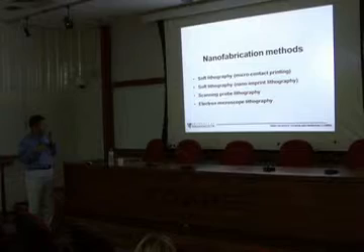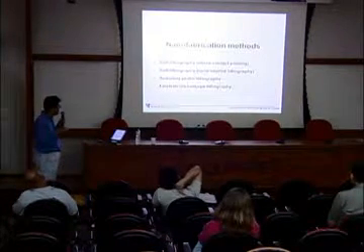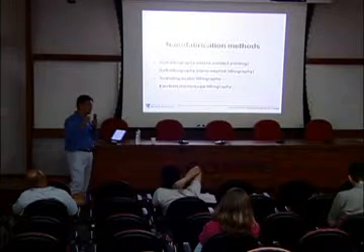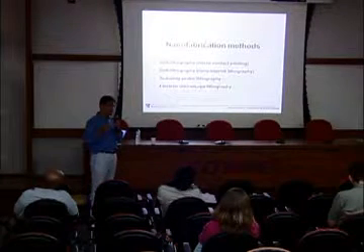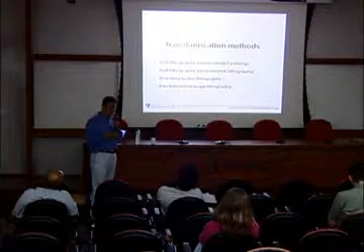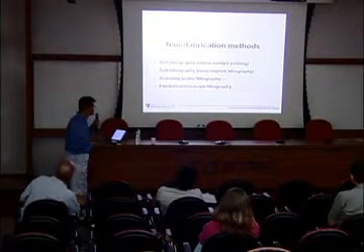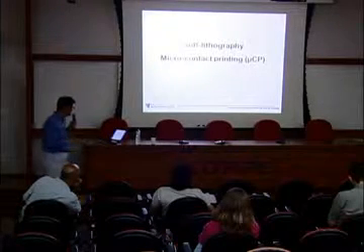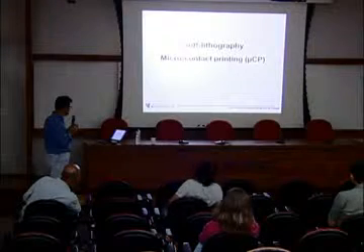And electron beam lithography is another tool that uses electrons to pattern a polymer layer. Again, the polymer pattern can be transferred to a metal layer or other layers to fabricate a specific structure. So let's see the methods one by one.